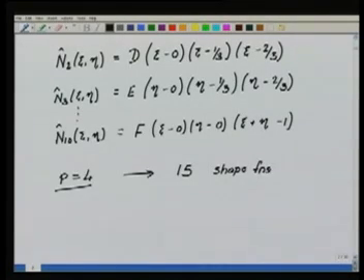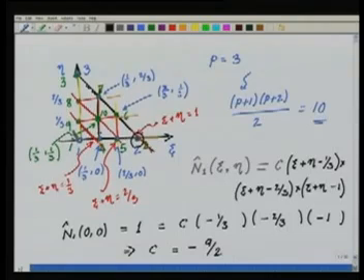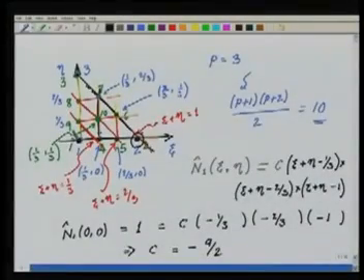Okay. So let me also give some notations. These corner degrees of freedom are called the vertex degrees of freedom. These degrees of freedom on the edge are called the side degrees of freedom, and this interior degree of freedom, which is the 10, is called the interior degree of freedom. And look at 10. 10 is only non-zero in the given element. Okay, it is going to be 0 outside this element.